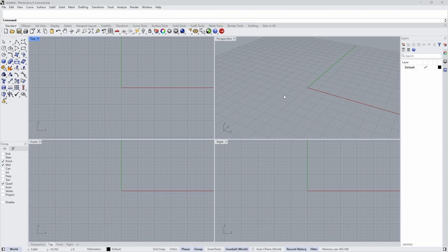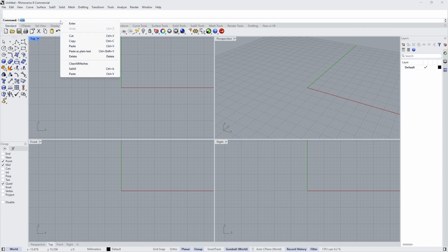Here is a really helpful tip. As you start typing commands, Rhino uses a fuzzy autocomplete to guess what you are looking for. For example, if you type CI, it will suggest circle since that's commonly used. This feature is brilliant when you are in the flow of designing and don't want to break your creative momentum. You can also right click in this area to repeat recently used commands, handy when you are creating repetitive elements in your jewelry design.